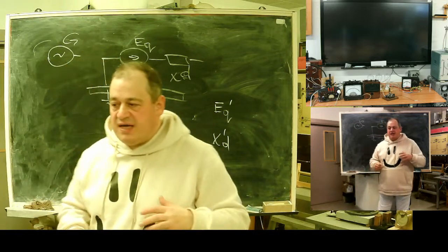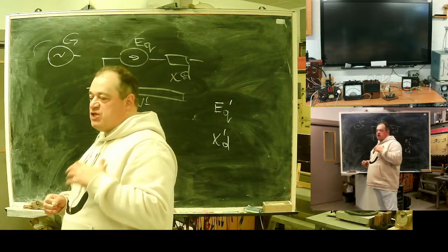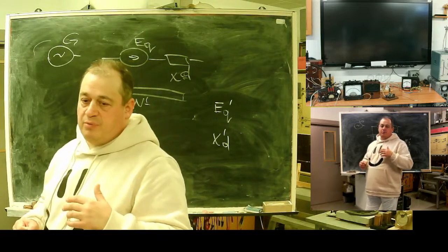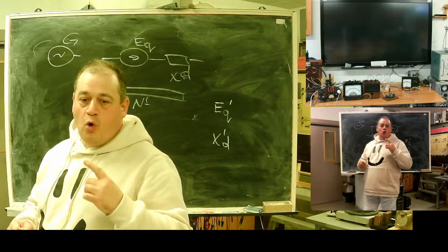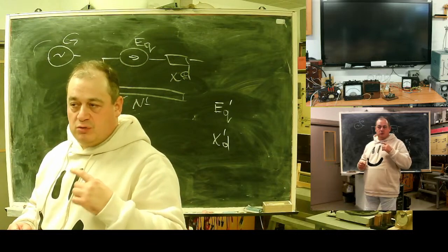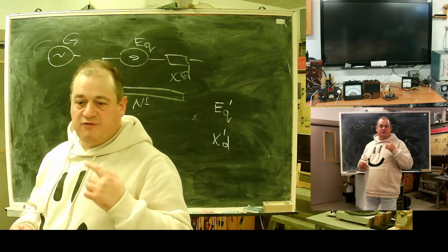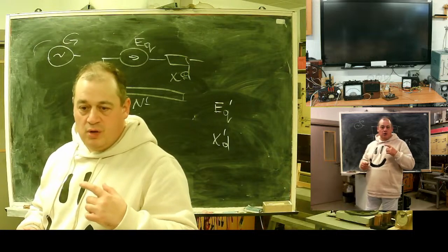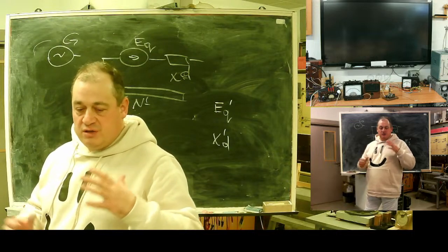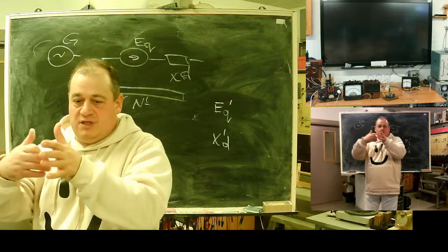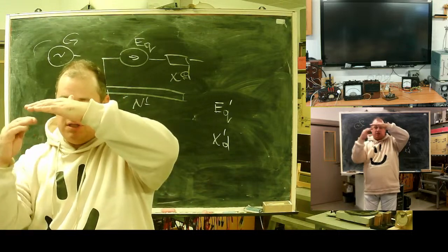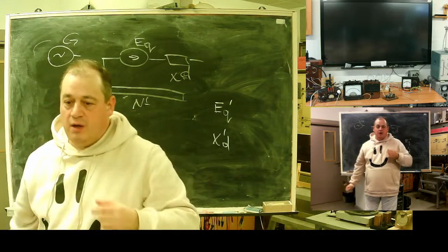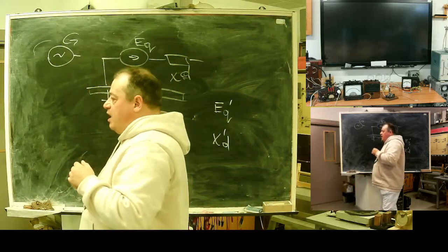It has a very negative impact, especially on hydro plants. When the mechanical load is low and supplied active power is low, the generator can oscillate inside the pole division.